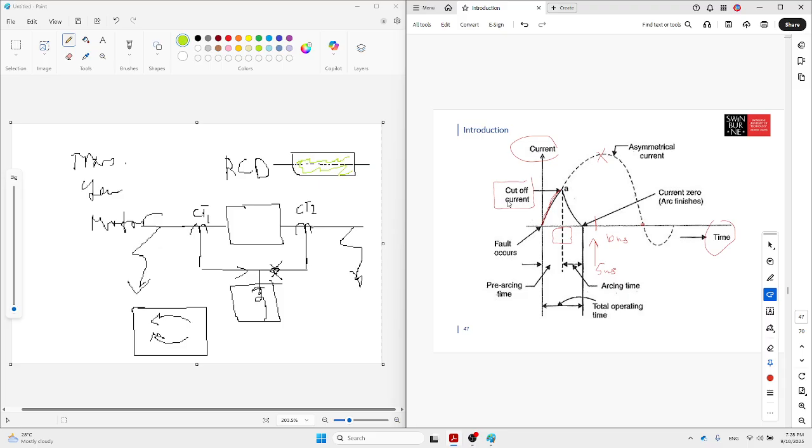It means that if the current increases and the time is set up by here, the material inside the fuse starts to melt. And this is the melting point. This is the highest time, okay? And then during the melting, of course, we have arcing, so the arc is still conductive. And then the current drops because of the arcing. Drop, drop, drop to zero.